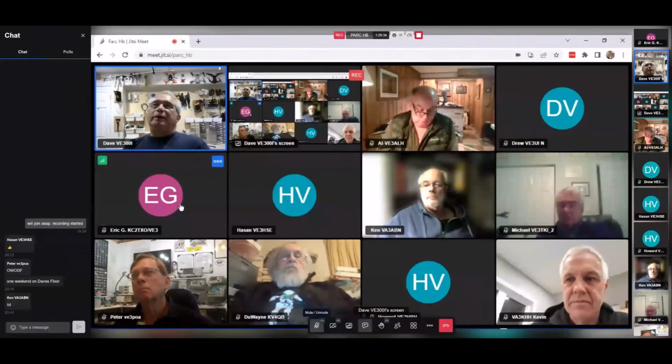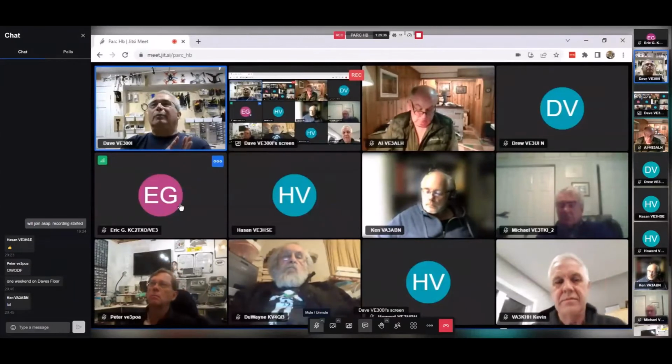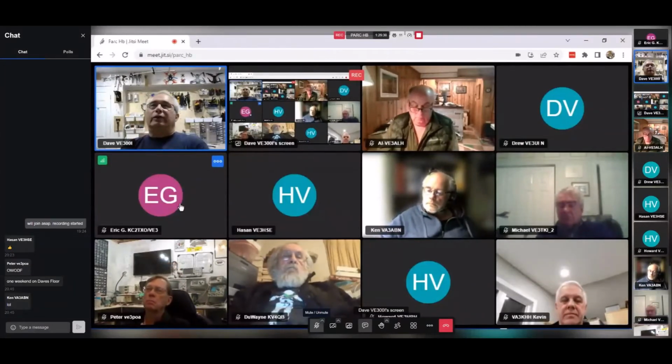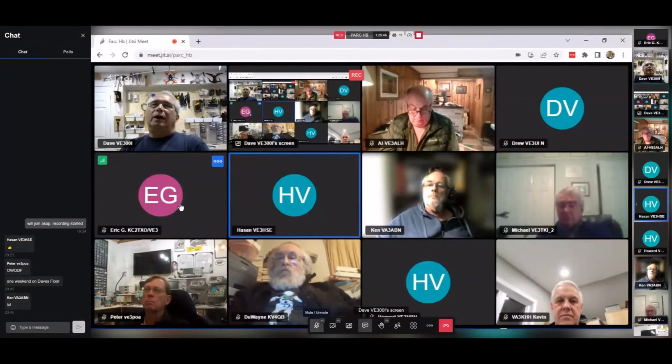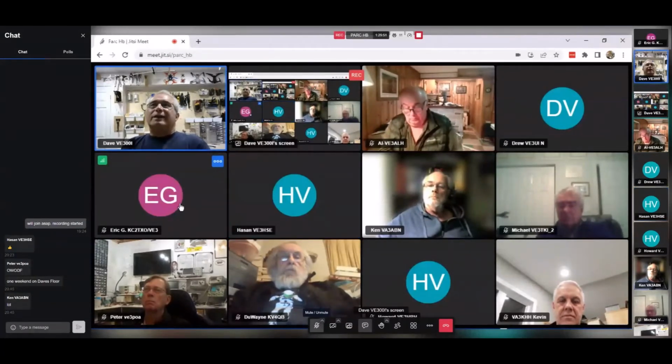Your PID output is going to tell you how much to pulse it to make it come back to straight. Was it like a megahertz or something? Like what, every microsecond? As I said, I had a 20 microsecond timer that was going off at 20 microseconds. So the fastest the pulse could be was 20 microseconds. That's the period, fastest. And then I could delay it up to a millisecond if I wanted.